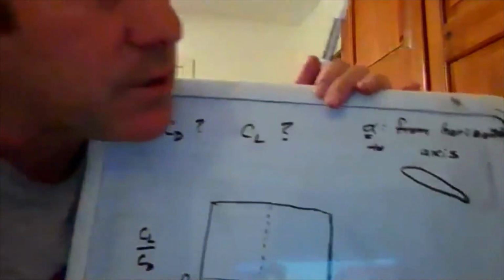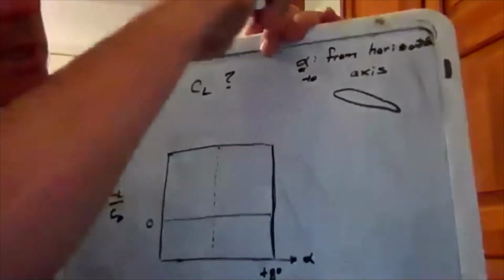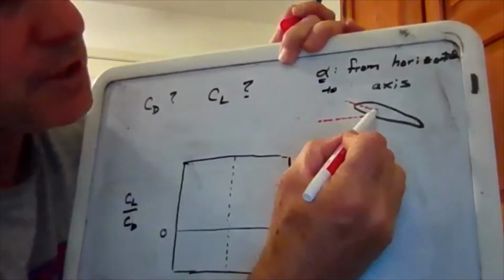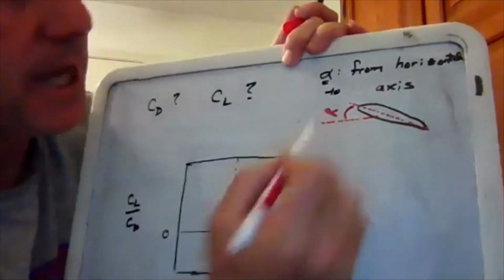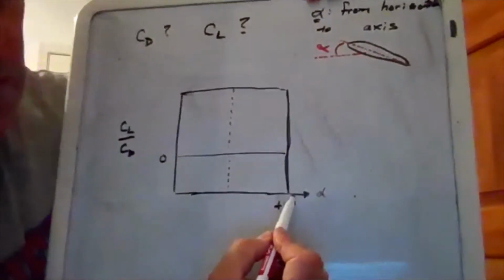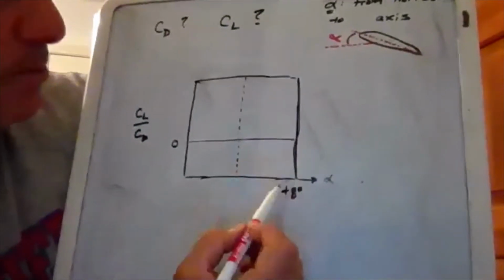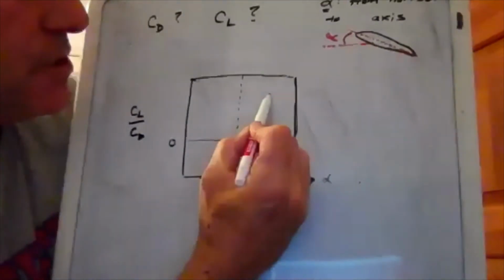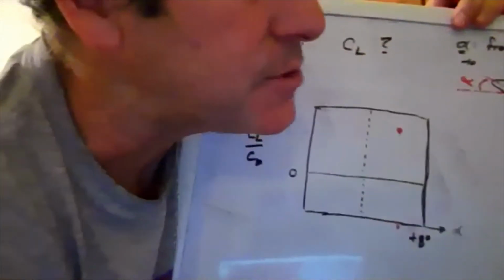One graph is 9.35a, which on the x-axis has the angle of attack, which would be the angle between the horizontal and essentially the line going through our wing there. So there's that alpha in that case. And alpha can be positive or negative. It's kind of interesting if you look at it, alpha goes up to 8 degrees. You don't want a wing much above 8 degrees according to this data. And you can get points at positive angles of attack where CL over CD is huge, on the order of 60 times greater.